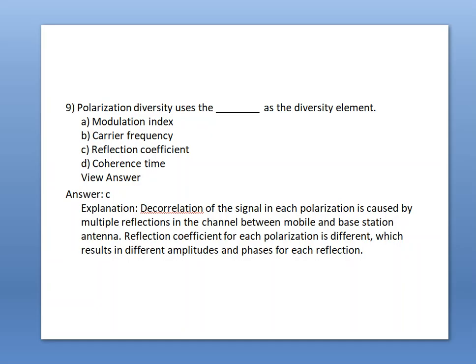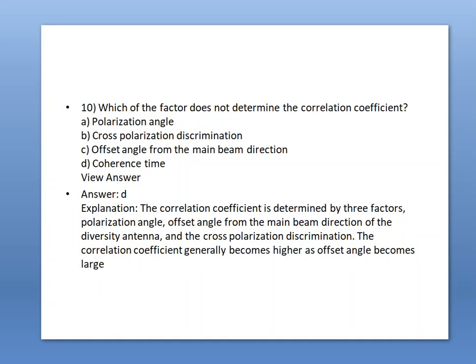Why? Because if it satisfies the maximum power transfer theorem, there are no reflections from the receiver to the transmitter, since maximum power is delivered to the receiver side. Otherwise, there is a possibility of a reflection coefficient. So the answer is C.